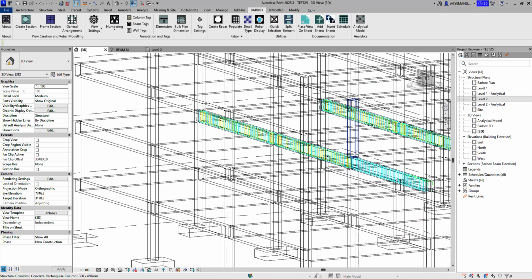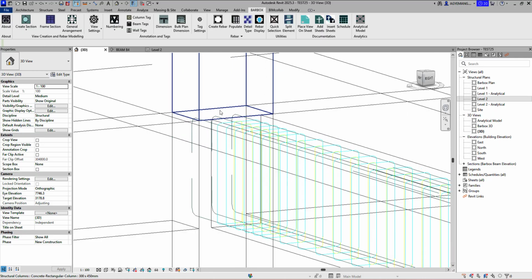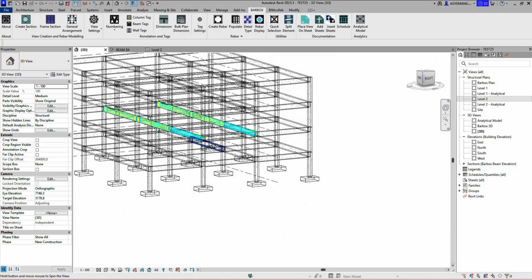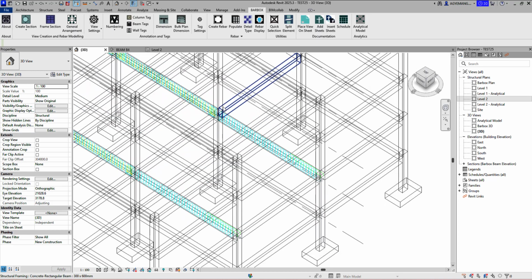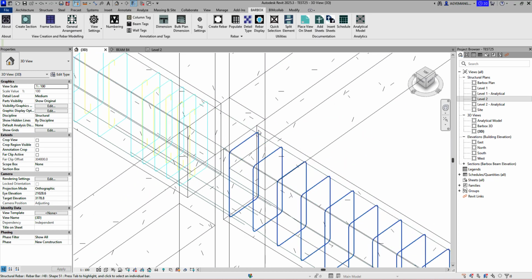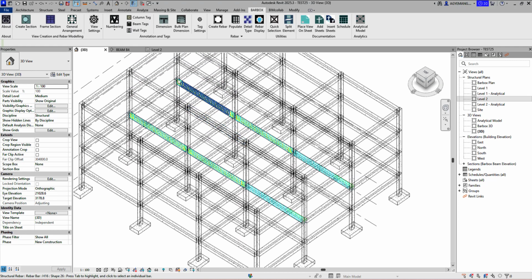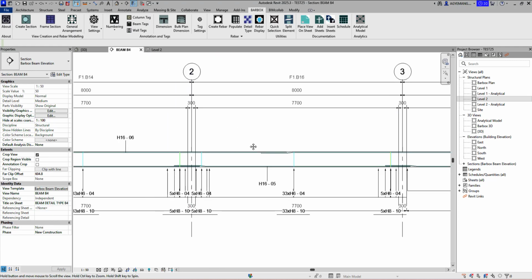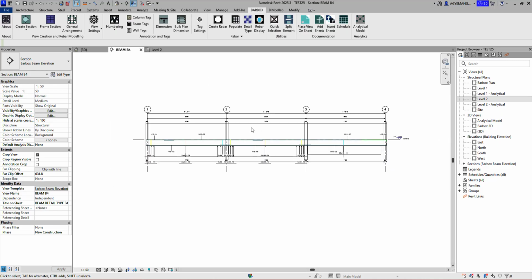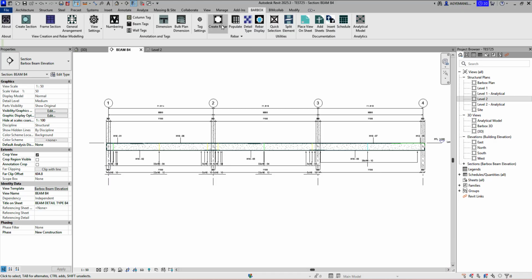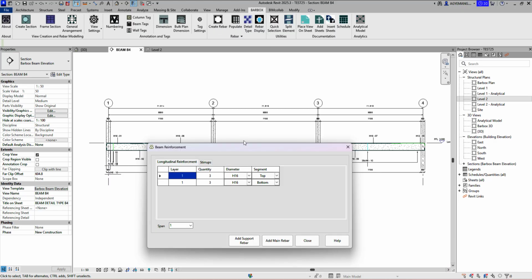And the good thing is, when these changes happen and you populate that same set, it goes with the new set types. That is, all the properties that have been changed will now be replicated in the other selected destination elements. Now, in the instances where you have to make some modification and addition of reinforcement, you click on the create rebar,